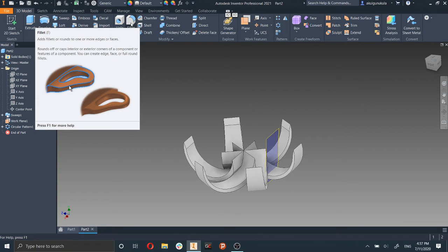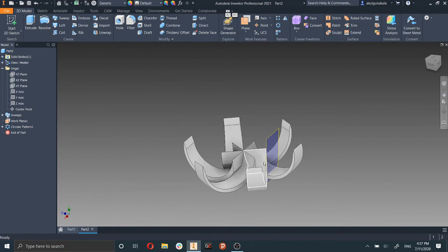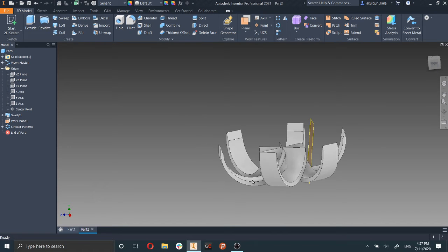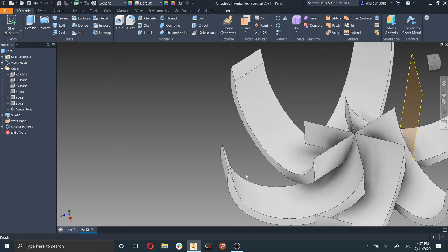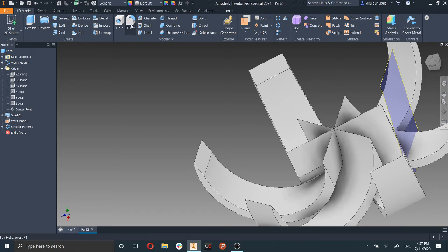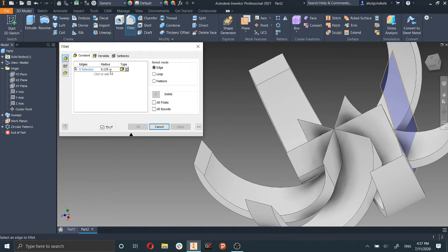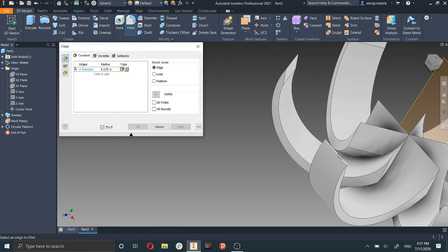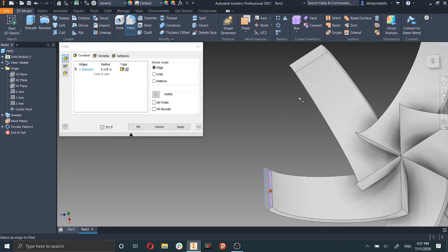It'll just round out the edges to make it look nice and to keep it safe. Even though this is only CAD, CAD will eventually be translated to the real world. So you want to try and keep machining safe and reasonable because getting the perfect cuts is going to be really hard. So you want to try and smooth it out. If you press that, you can change the diameter that it's going to be, and then you just select the edges of things.